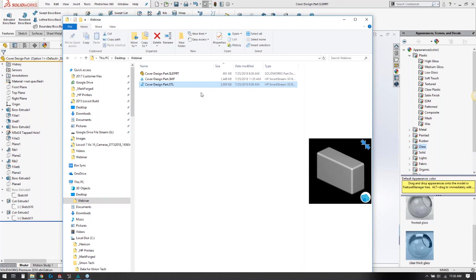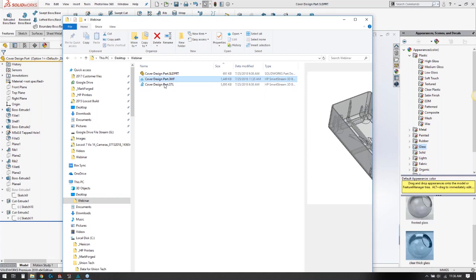Two bad things about STLs are they're a larger file size, and they're less likely to export correctly. A lot of times with STLs, you can get parts that are not watertight, and that just adds more confusion and more headache later down the line if you have to fix the STL. The benefit of the 3MF is a smaller size, and the algorithm for making the conversion works better. So you have fewer problems down the road.